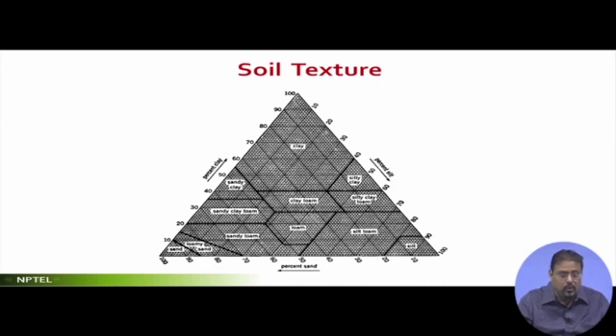If you go more into the clay zones, very interestingly, about 40% is silt, but we still consider this portion of the soil as clay. That means this will be termed a clayey soil, that means we have more of clay. If the quantum of clay is much greater in proportion, that soil becomes very, very weak in terms of stability and also in terms of vegetative capability.